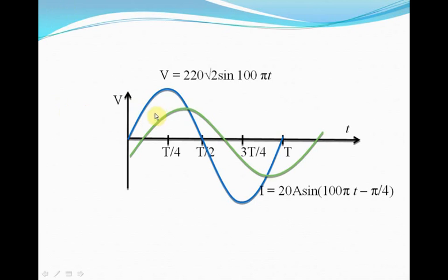Again, as you can see, the cycle for the voltage starts at the origin. The same exact cycle for the current starts slightly later in the case of the electric current. It starts at a phase angle later. Understood? You can even label all these points at which the electric current graph intersects the time axis, isn't it? So you can see that the electric current is 0 at time period divided by 8, and then it increases and increases, and it again becomes 0 at 5T by 8. T here represents the time period of both the electric current and the potential difference variation.